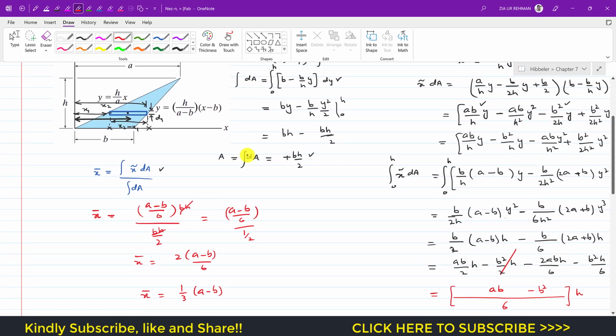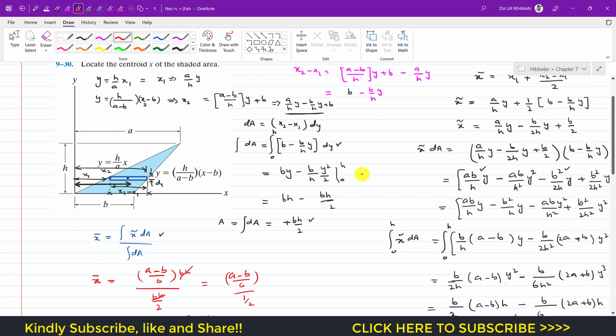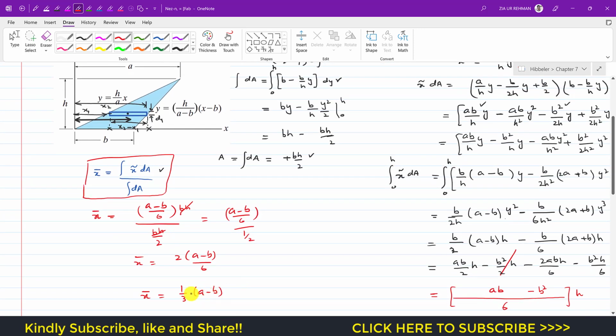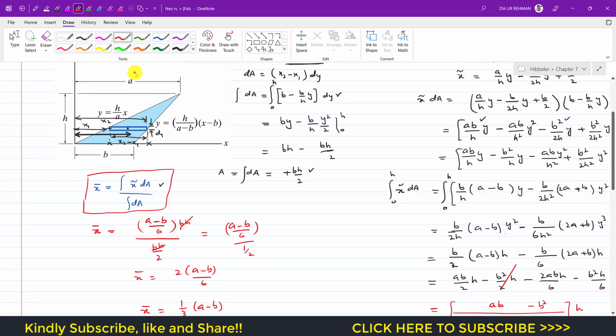This is the x bar of the centroid of this blue shaded area. So this problem is quite difficult in terms of doing all these simplifications. Otherwise, if you know the methodology, then this is the x bar, that is 1 divided by 3 into a minus b. So if we are given these lengths, let's say a is given as 5 and b is given as 2, then we can find x bar.